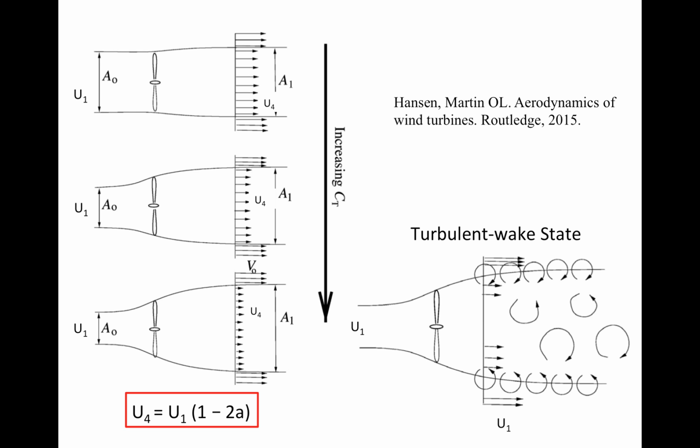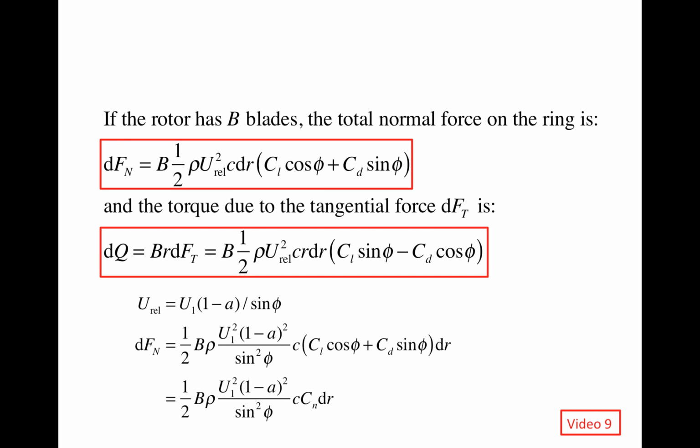actuator disk model. So in this kind of case, when A becomes too large, we need to account for this situation. And how do we do that? We can use empirical relations obtained from labs, real observations, or wind tunnels. But before we talk about the corrections for such high values of the axial induction factor A, let's introduce a new quantity called the thrust coefficient.